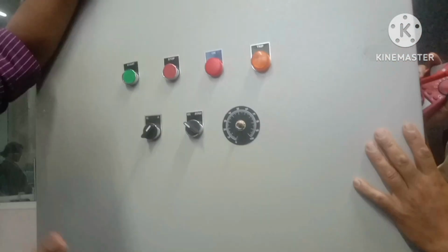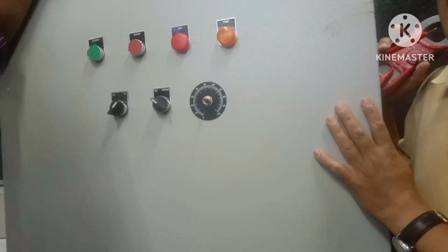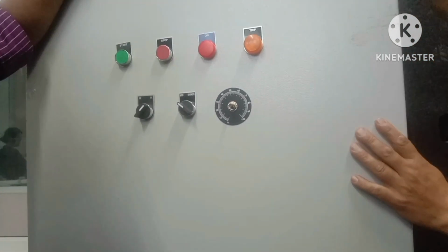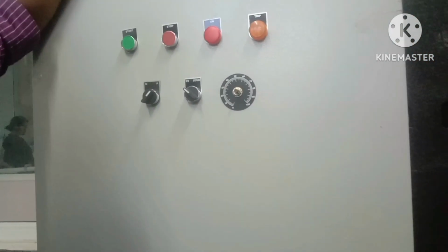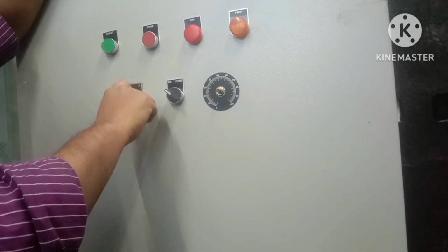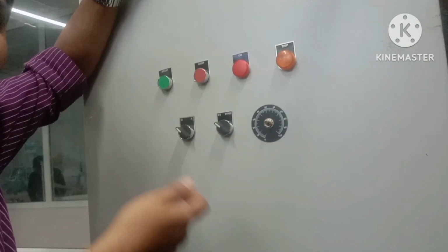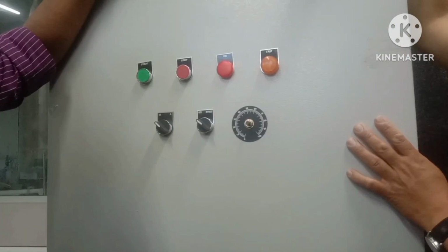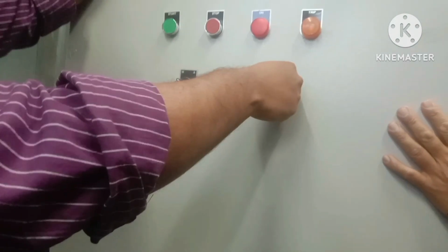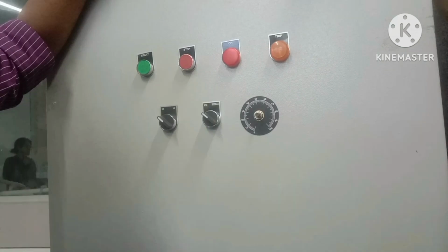So there is also a thermostat present in each room, as I showed you there; we will be visiting one more time. If they want manual operation, they do not want the auto operation, they want to control by themselves, then you will put it into manual mode and to the VFD. In that condition, you will keep an ideal speed of between 25 hertz to 30 hertz, not full speed.